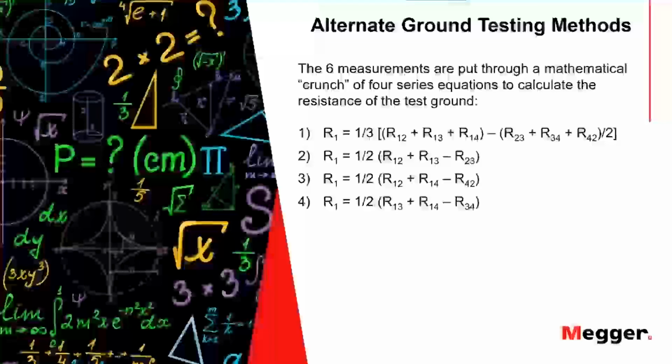But if you have a relatively well-developed ground tester, then you should have this capability built into it, where for this method and the other methods that we've looked at, you plug the test results into the software, and bingo, very quickly, you're not sitting there with a calculator and a pencil and paper. The calculations are done for you, and you can put it in a test report. You can send it to a client or whatever.